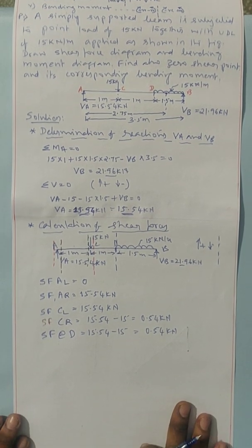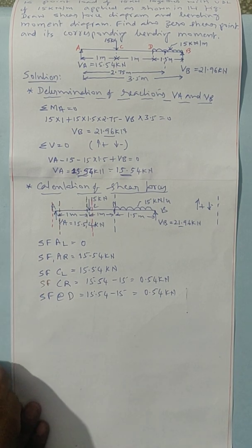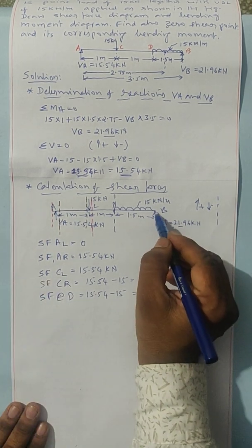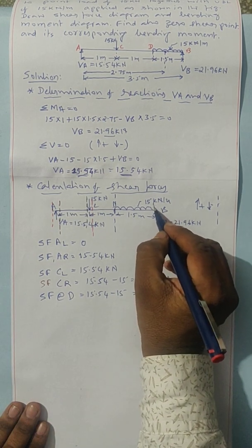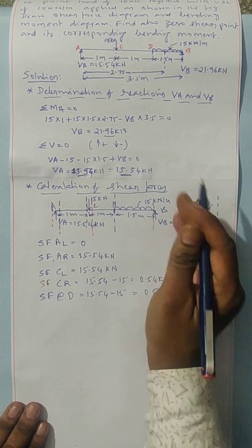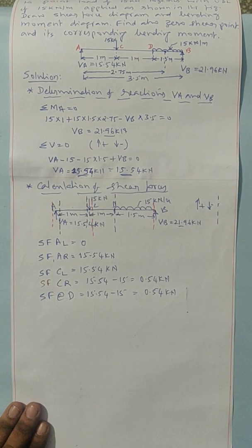Now, shear force B left. Shear force B left means here, just left of B. I have to consider all the forces left of this, upward positive, downward negative.